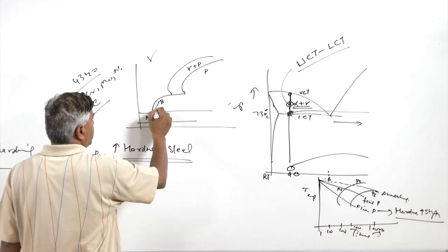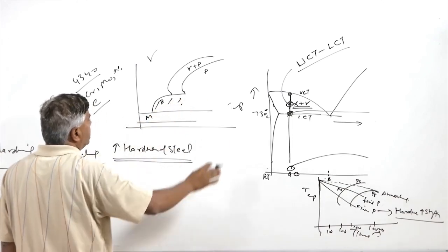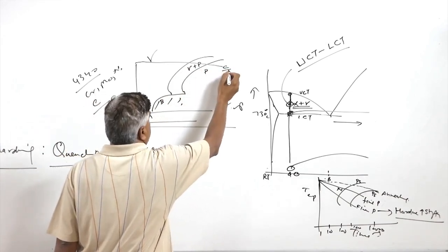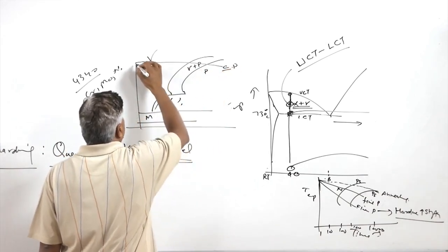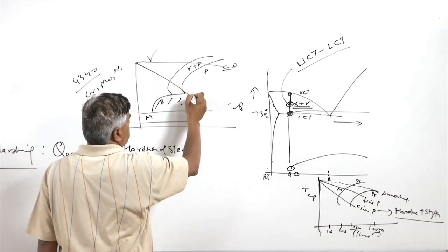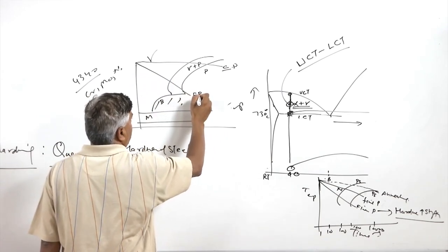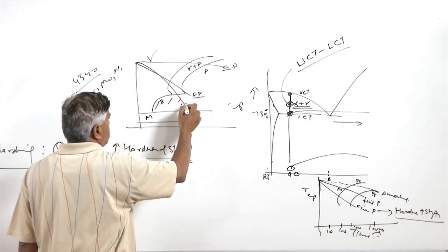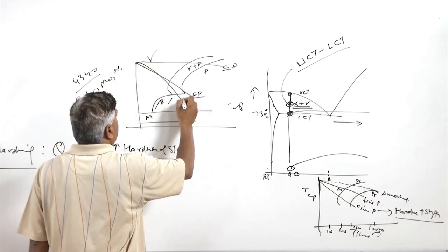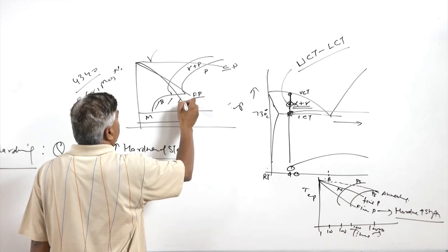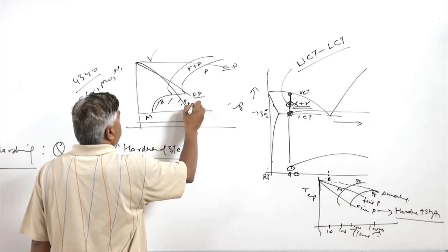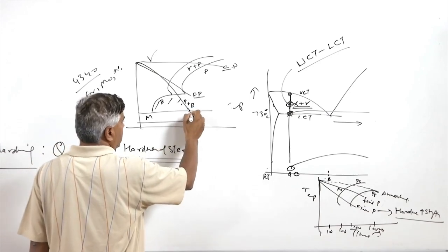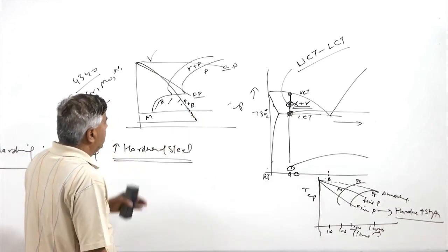So there are different zones which are formed depending upon the cooling rates. If the cooling rate is like this, we may get the coarse pearlite. If the cooling rate corresponds to this one, then we will get the fine pearlite. On the other hand, if we are passing through this zone, then we will mostly get pearlite plus bainite, and if some amount of austenite is left, then transformation will occur into the martensite.